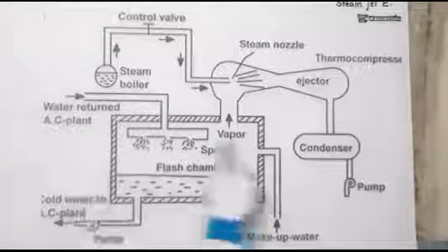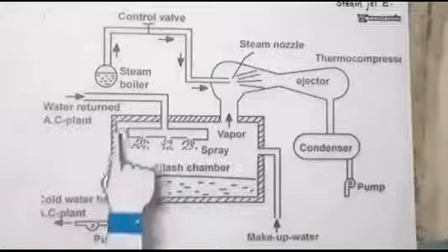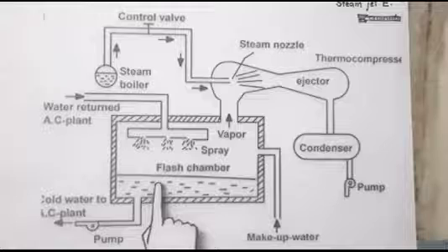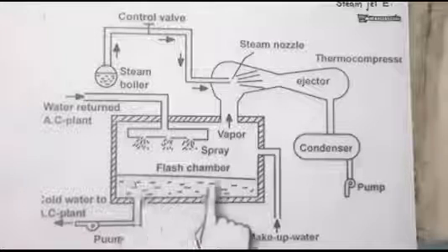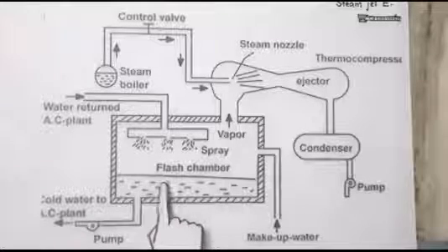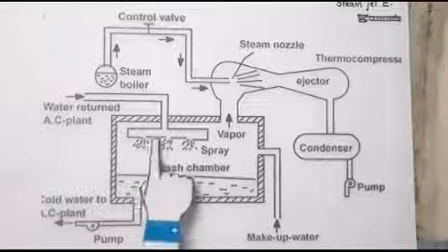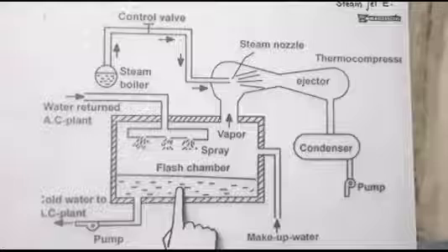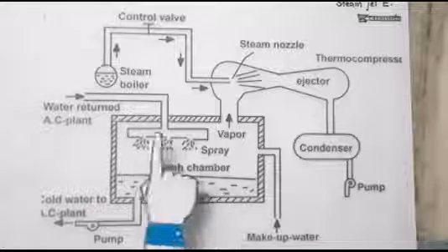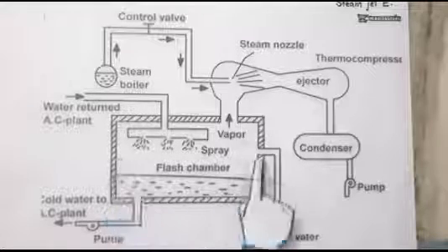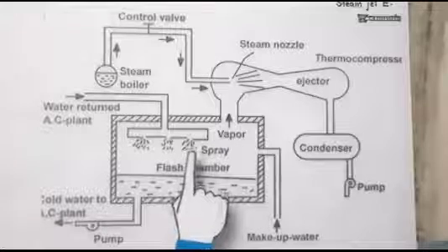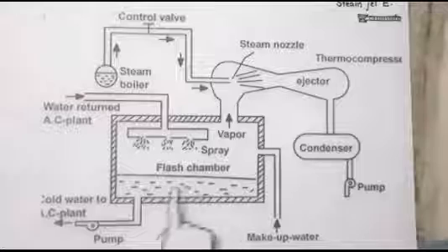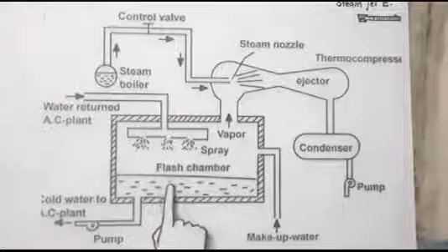But as all the walls of this chamber are insulated, it will not gain any energy for evaporation. So it gets that heat from itself and starts evaporating. When evaporation starts, this liquid cools down. Overall, we want the pressure of this chamber to decrease, and that will start the evaporation process for the water.